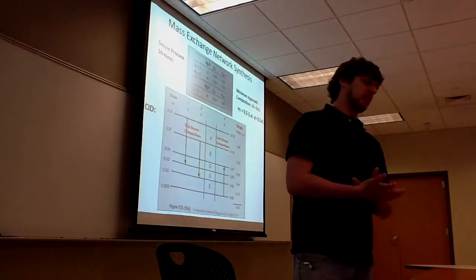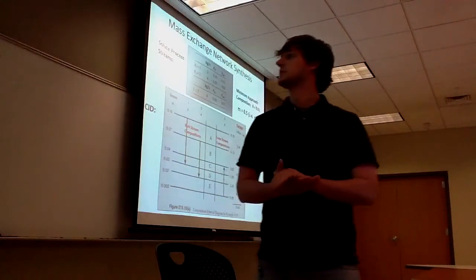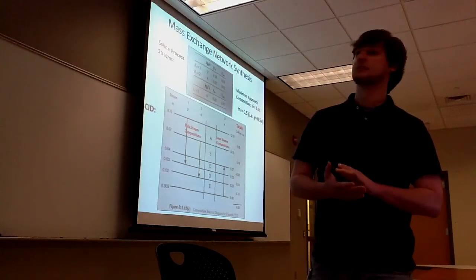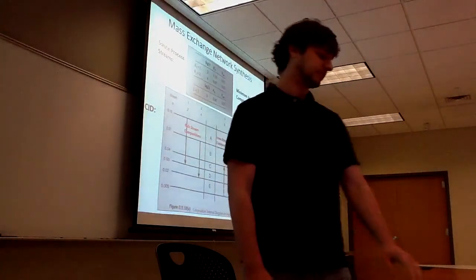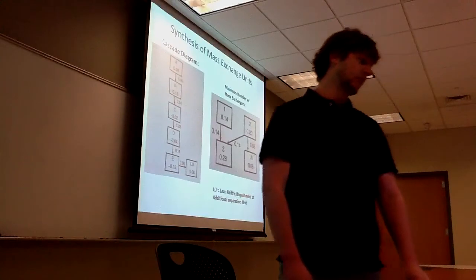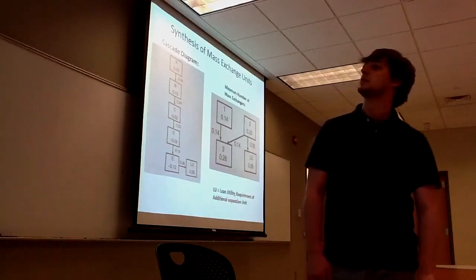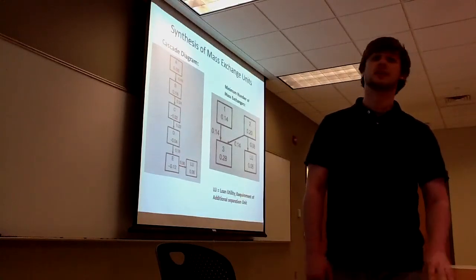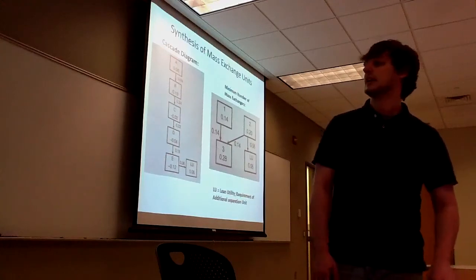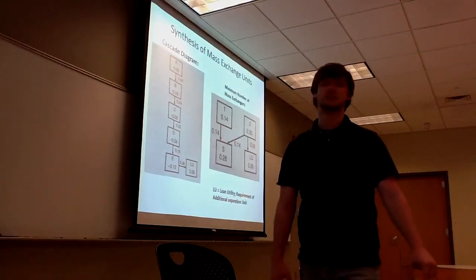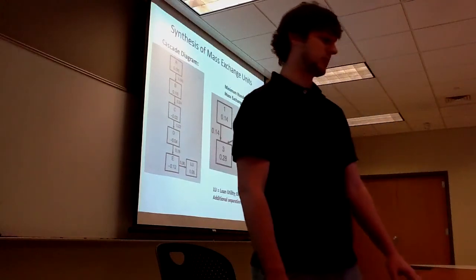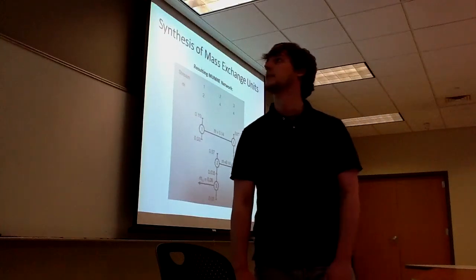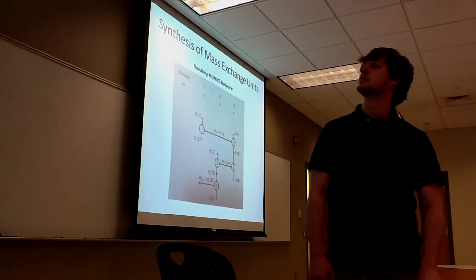Just like in heat exchangers, you're going to have your rich streams on the right side and your lean streams on the left side. And the totals at the very end, you're going to sum those, which is going to be your interval mass flow rates between those. Lastly, we have our cascade diagram coming down, the intervals in between, of course. And then the minimum number of mass exchangers is going to ultimately result with the 0.06 at the very left. What that means is a lean utility, and it says you're going to need an additional separation unit, such as a gas adsorber or something, to take care of it. And then synthesis, finally, after you go through your MUMNE network, you have this result.